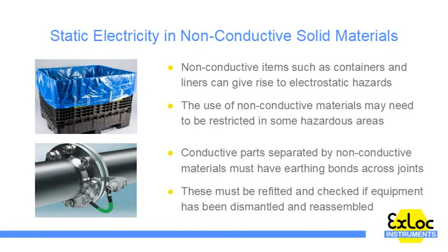It is good practice to minimise the use of non-conductive materials in hazardous areas, and today many formerly non-conductive materials are available in versions which allow electrostatic charge to dissipate to Earth, and these are known as static dissipative or sometimes anti-static materials. Choosing static dissipative materials over their non-conductive equivalents will greatly improve the ability to control static.